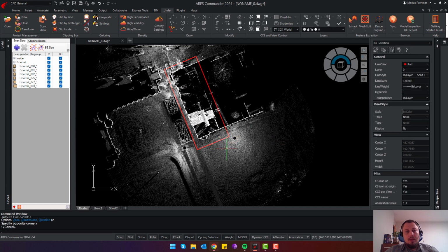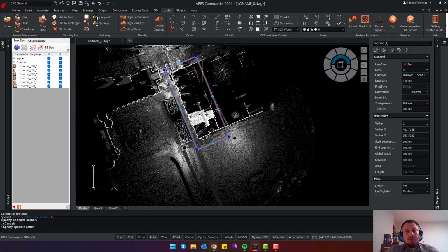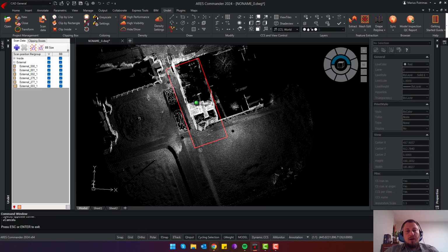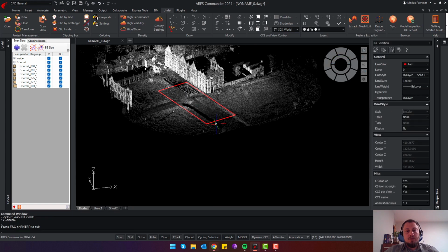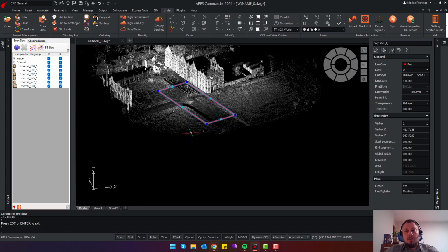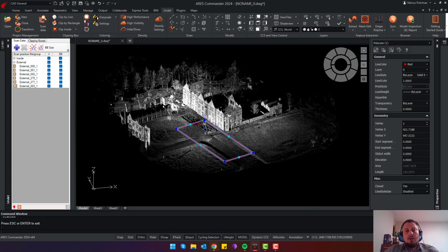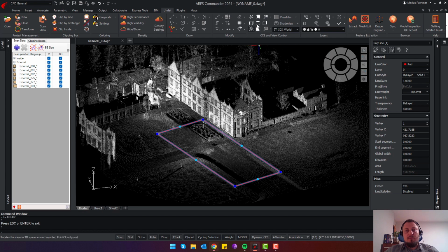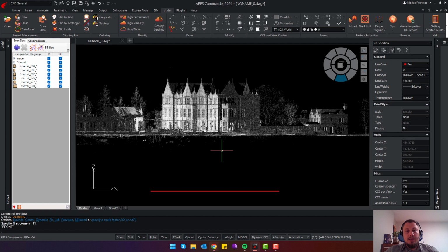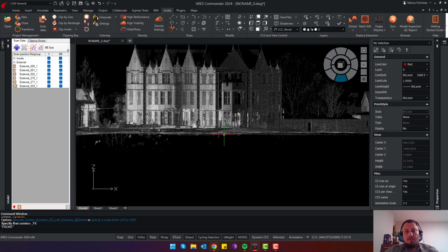So in this project, I will have 4 projections for the elevations. And now, if we are leaving this reference outline in the floor plan vectorization at the 0 elevation, when you're vectorizing the elevations, you can rotate the view from the side and just check the global level of your point cloud.